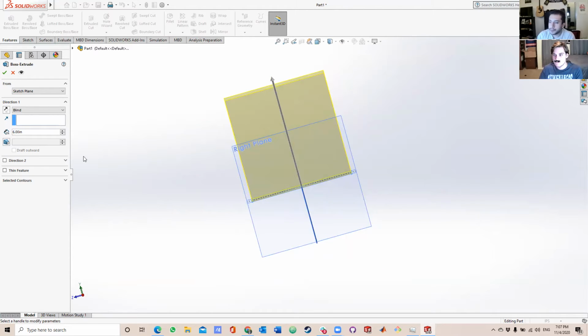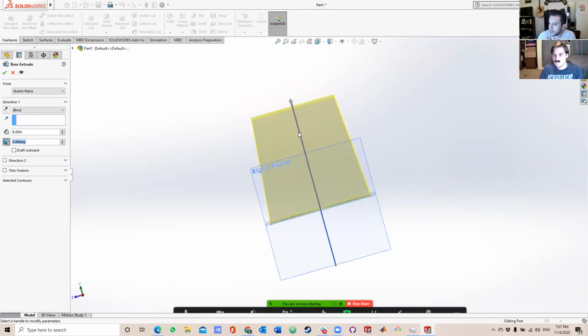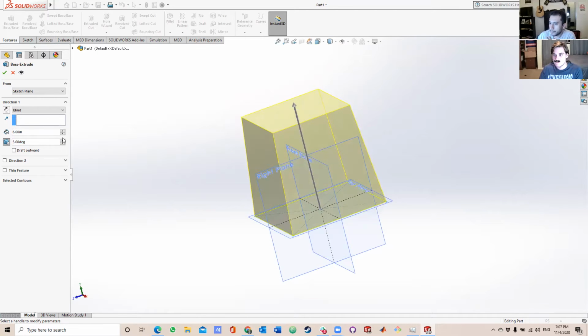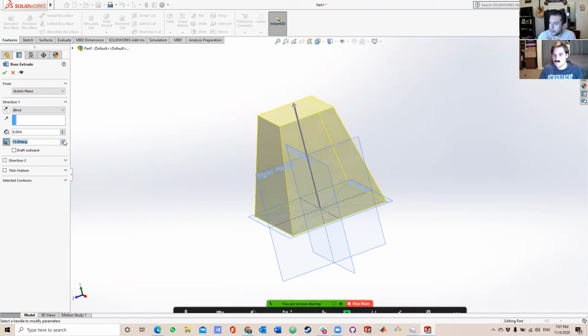Another thing that you can do with extrusions is drafts. Let's say that I wanted to go down to a point. I would like my roof to be smaller than the base. I can use this extrude function and, by degree, push it smaller and smaller to a point.